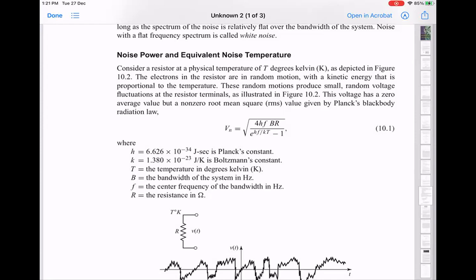So the question is, where is this noise coming from? It's coming from the internal circuitry of the amplifier. That's the picture. Now, depending on how the amplifier is designed, this noise could be higher or lower, and there's actually a quantity which specifies how good or bad this is. The definitions we are going to see are essentially to understand how this is represented in typical microwave frequency amplifiers. Okay. So this property is often called the noise temperature of the amplifier or the noise figure of the amplifier. They both represent the same thing, just in different quantities. That's basically what we will see.